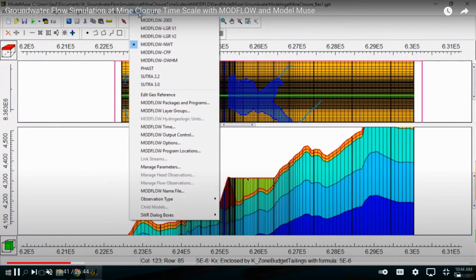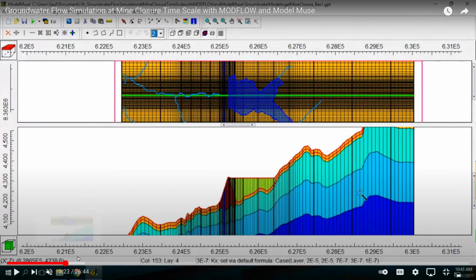where these individual cells, I don't need the background here of how to do it. Each of these individual boxes is the little control volume that flow is going into, flow is coming out of, and the difference between those would be a net accumulation. And so if you write an equation for each one of these boxes and then solve them all together, you can get the flow distribution throughout this system.